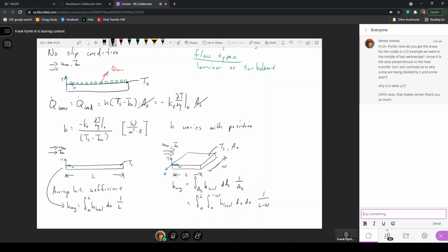So that's how, for this specific case, where I've indicated bounds in the X and the Z directions. And here I'm integrating through the X and Z directions because that's the plane in which this surface is lying, in that the positive Y is up and away from the surface. This is how I would get the average value of the heat transfer coefficient. So here, these two expressions are just general expressions on how we would calculate the average heat transfer coefficient that exists over a given surface.